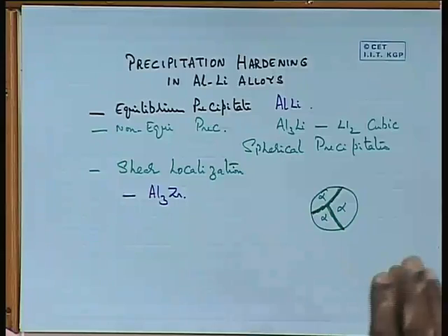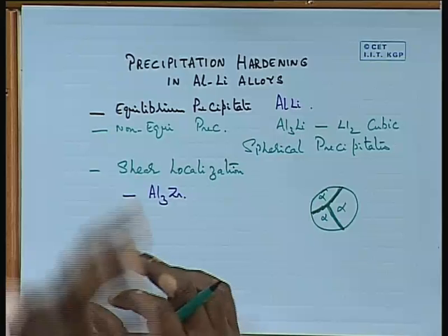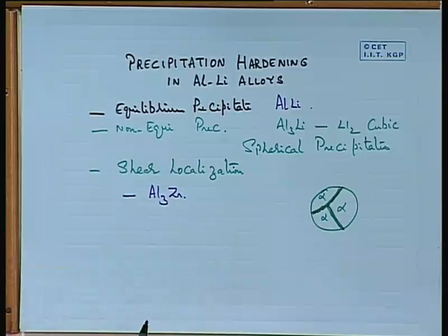So if you look at a precipitate which is coming out and measure the lattice parameter of the precipitate and know the lattice parameter of the parent phase, if the lattice parameter of the product phase is largely different from that of the parent phase, then we say the misfit is very large. And this misfit is going to decide whether you are going to get coherent, semi-coherent or incoherent precipitates. Even if the structure is same, keep this in mind.